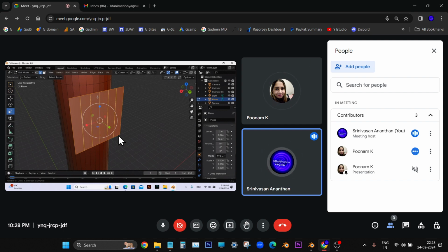Yeah. This is enough. Five is enough. Now left mouse button, one click. Yeah. Escape. Immediately escape. That's all. So this you can always follow: one left mouse button click and then escape, so that you won't add one more edge, or you won't move this set of edge loops that you have added. Now we don't need this loop cut and slide.